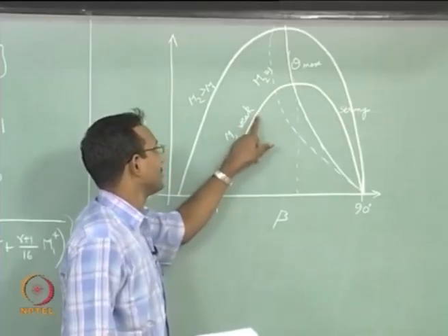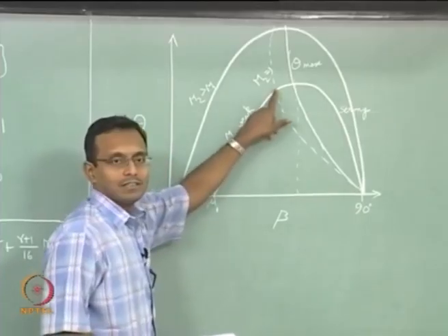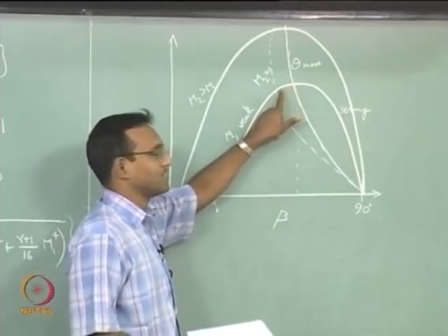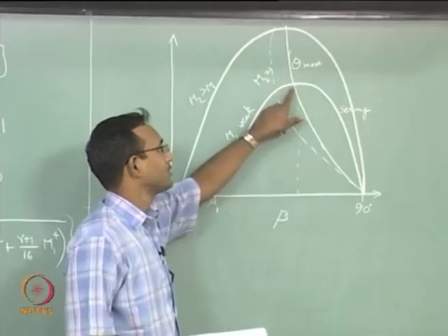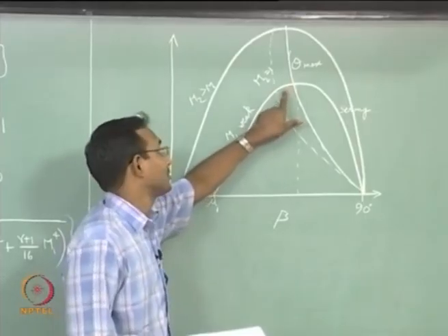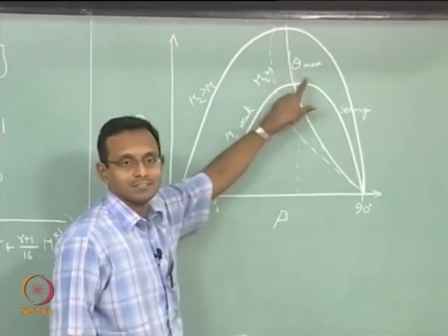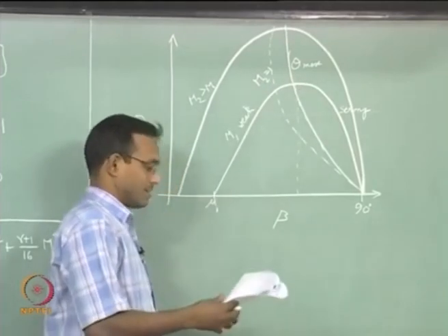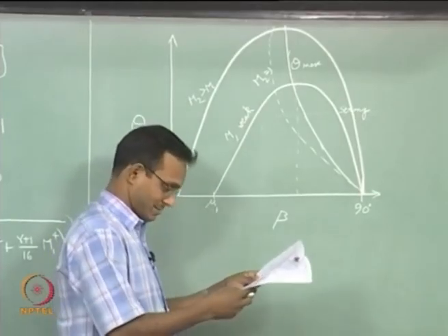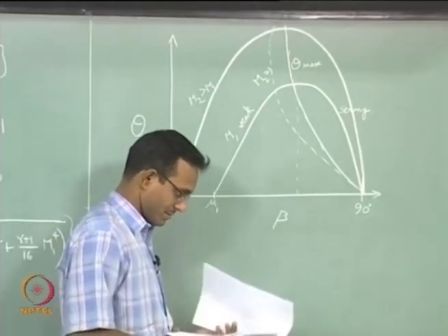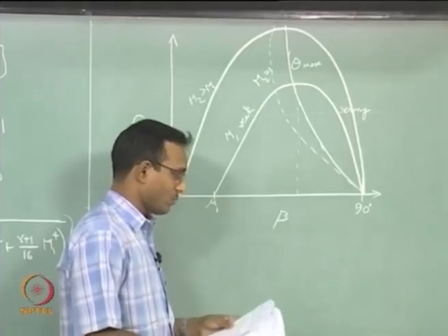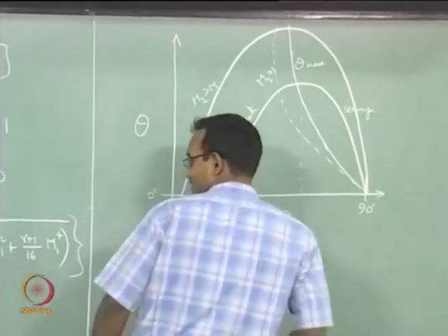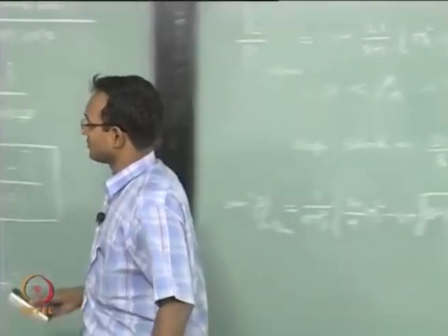So, I basically have a weak solution for low thetas, which will have supersonic flow behind. For thetas very close to theta max, when theta is very close to theta max, you may have a subsonic solution. You have to be careful looking at that region. It may have a subsonic solution behind the shock. Okay. You just have to be careful about it a little bit. Now, I want to look at why there can be two solutions for the same deflection. So, we will go to that side and we have to start drawing pictures.